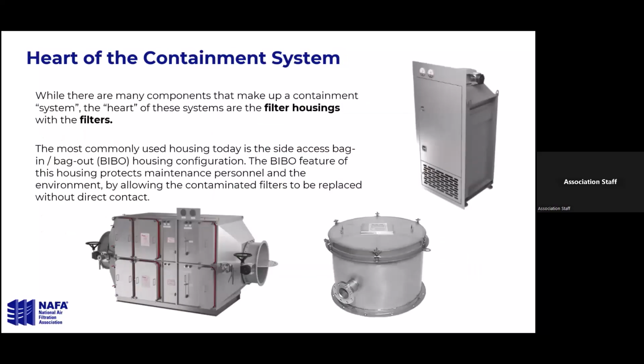So the heart of the containment system is going to be the filter housing and the filters that go in that housing. The most common type of containment housing used is going to be the bag in, bag out housing. It's generally a side access housing.